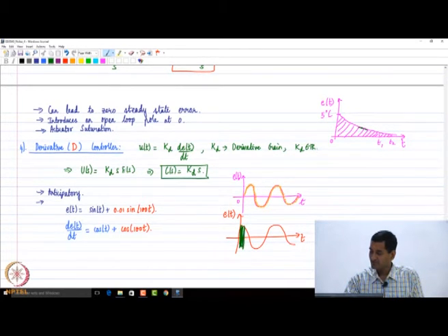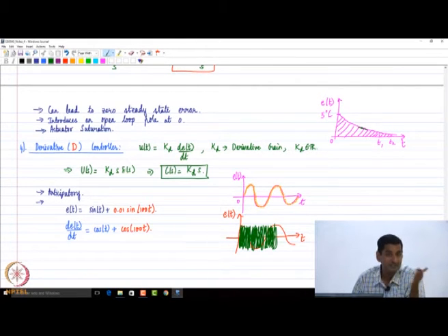So cos 100t is going to be like a band. I'm just drawing relative to this, but you get the point. It's going to just mask this signal. As a result, your controller is going to fluctuate very, very fast, which is not the intended result. That's due to the fact that the derivative controller may amplify high frequency, low magnitude noise.